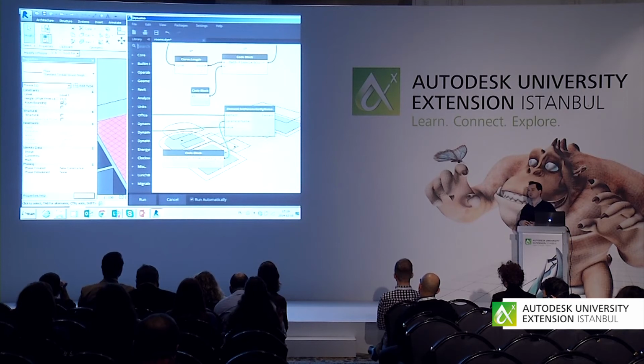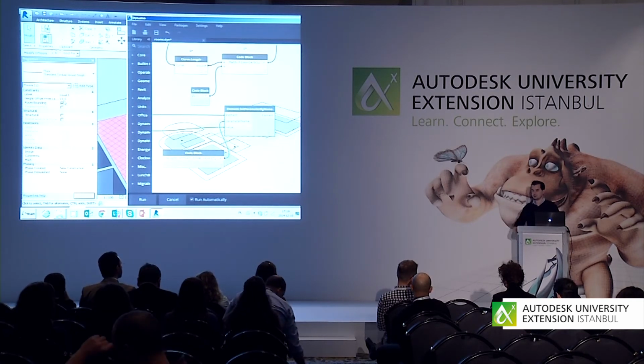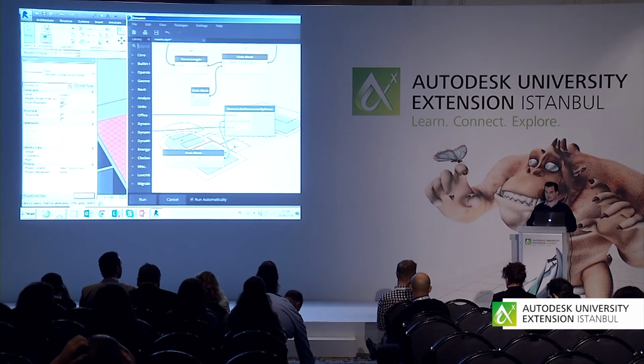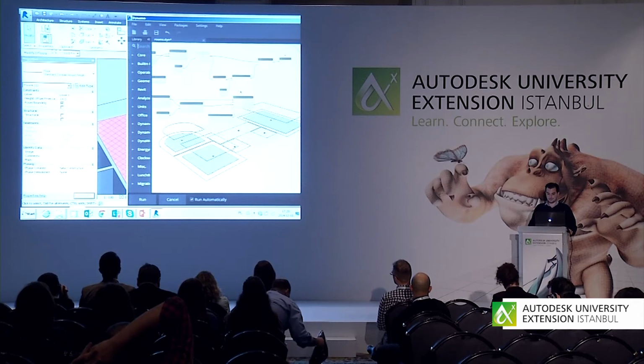With this I can also be sure that my walls have the correct offset, and my columns always have the same offset, either top offset or bottom offset. My finishing layers are not overlapping with existing structural floors, but are always at the correct level. I don't have to worry, I don't have to check and double check.